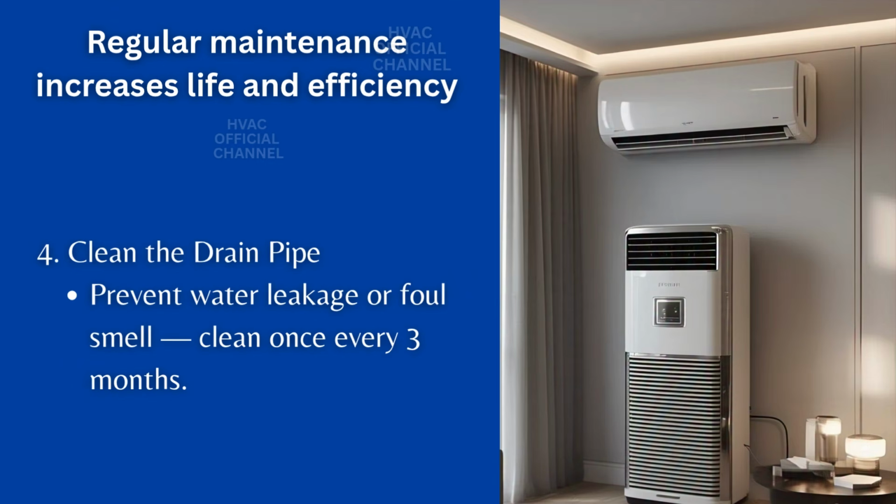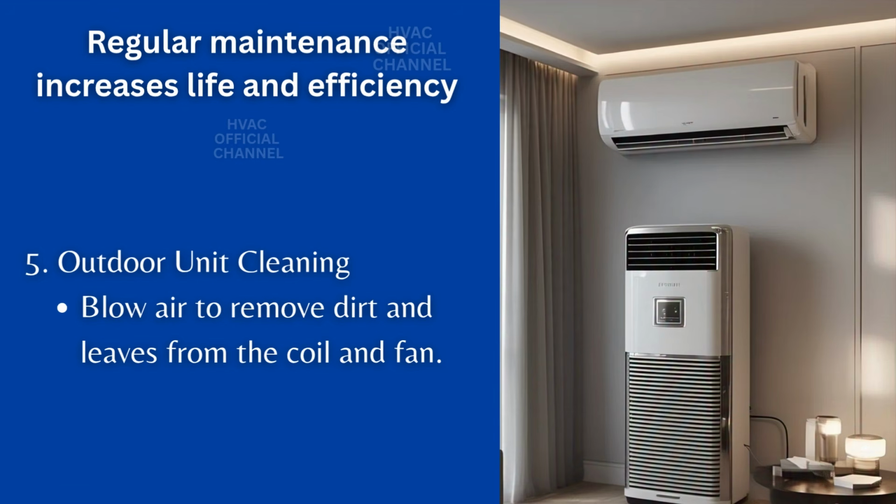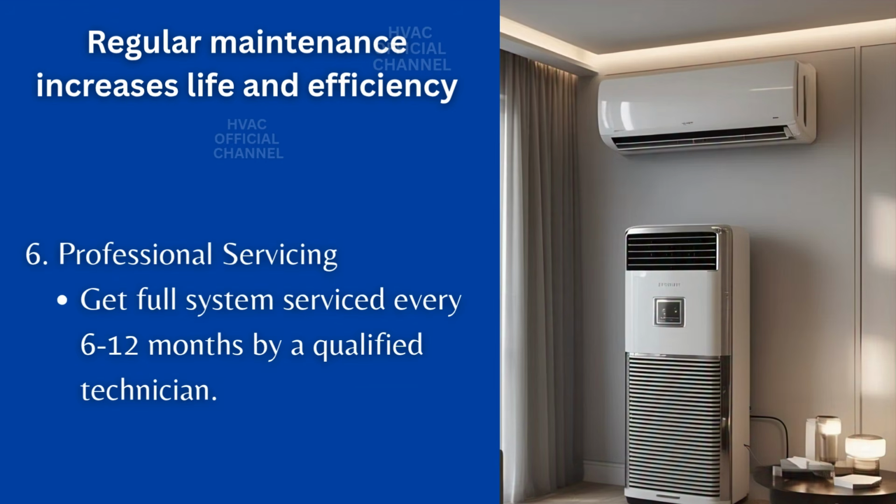4. Clean the drain pipe. Prevent water leakage or foul smell. Clean once every 3 months. 5. Outdoor unit cleaning. Blow air to remove dirt and leaves from the coil and fan. 6. Professional servicing. Get the full system serviced every 6 to 12 months by a qualified technician.